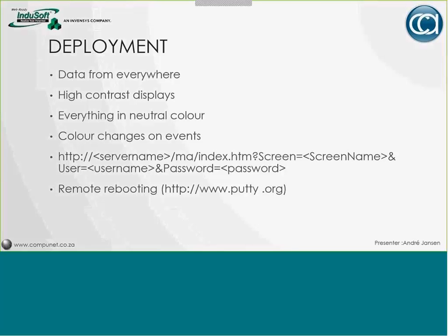The project required us to display data from various sources. With using InduSoft Web Studio, this was easily accomplished with database and OPC support built directly into the product. Tags from 5 different PLCs were collected via an OPC server, and some data was collected from an existing Microsoft SQL database. We developed some screen symbols, and I'll shortly show you in the InduSoft project what they look like, and used high contrast colors to enable the screens to be easily readable from a distance.